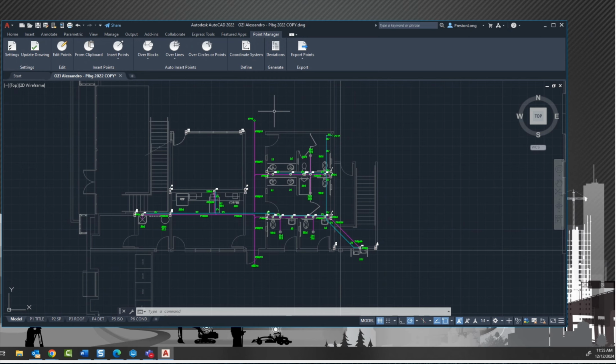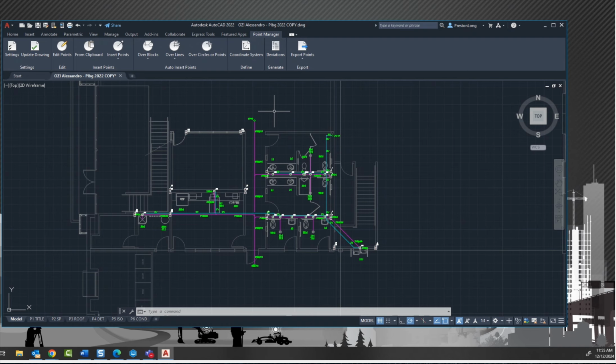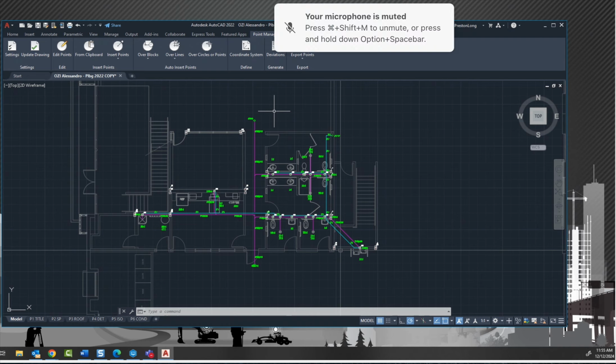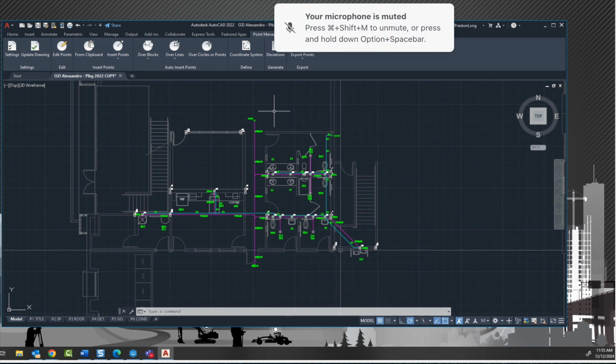Okay, so I could put it in the description so that when they're laying out in the field, they could look at it and see the hanger needs to be at this elevation, you know? That would be what you would do. So to set your bottom of pipe, your BOP, at a certain elevation.